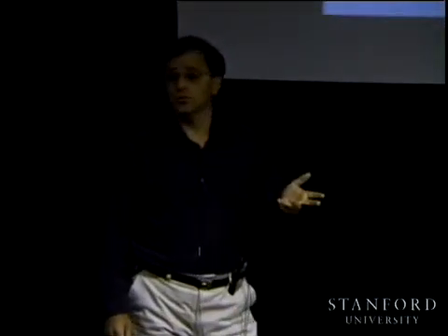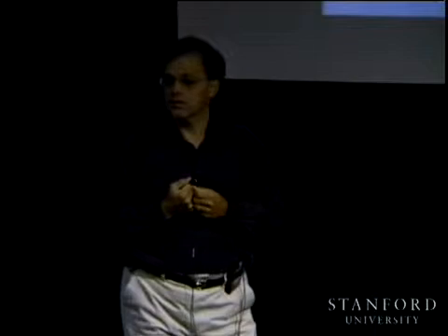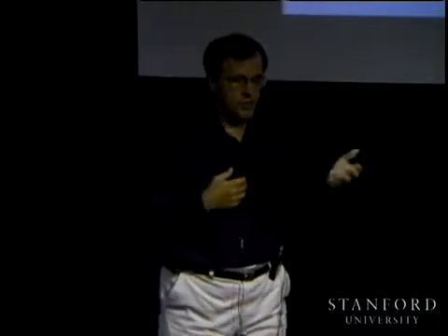Okay? And the other major problem is that we have discontinuity problems here. Because if we are planning in Cartesian space, we have our nice straight line that we are following in Cartesian space. We convert to joint space. It might turn out that it is impossible to do that in joint space. And we'll see some examples right now of this kind of problems. So both spaces have pluses and minuses. In reality, you usually use some sort of a hybrid approach to limit the computation, but also to make sure that you're not colliding with obstacles along the way.